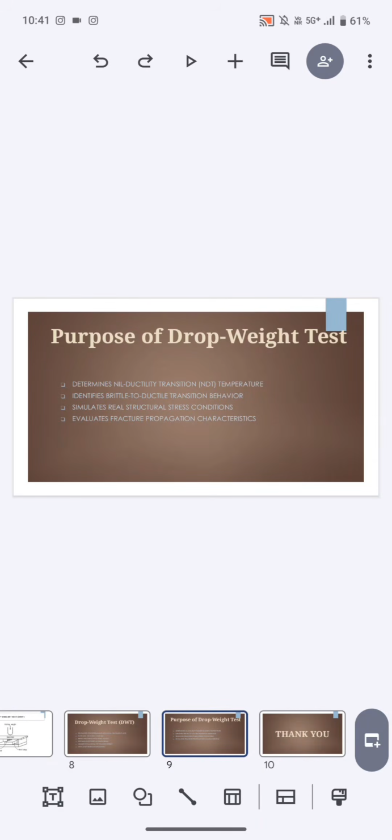The drop weight test, DWT, was developed specifically for determination of NDT on full scale thickness. A short bead of brittle weld metal is deposited on the surface of a plate, typically 90 by 350 by 15 to 25 mm thick.